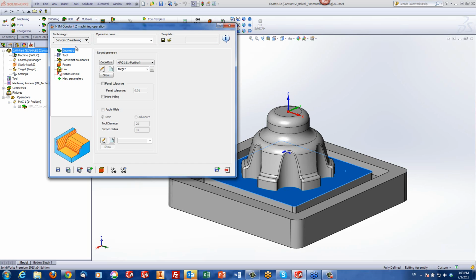When it finishes that step, it goes down to the next step, doing another profile cut on that boundary. That's all it really is. It's very simple, works just like a profile, just on each step as it goes down. It looks at whatever the boundary geometry is on that particular step and then goes further down.